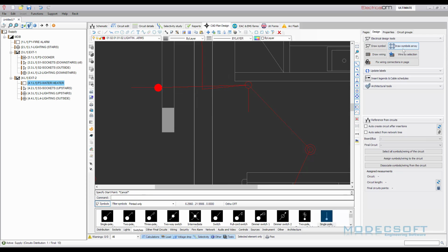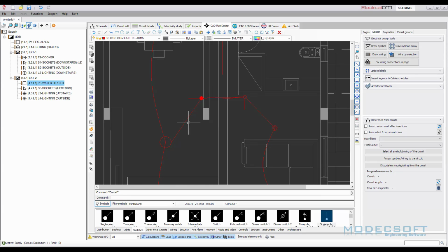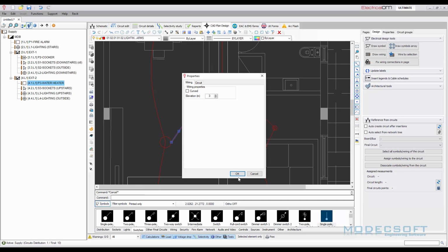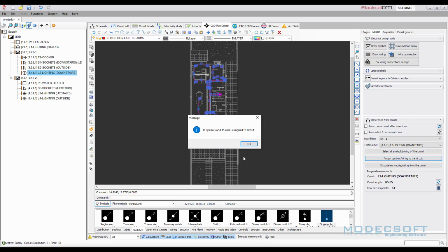I'm going back here and again from here. I want to go back to this lighting point as well. I can control the elevation by double clicking and fixing it properly. Okay, now because we have only one circuit for these lighting points, we can just select them all together and going to our tree network view, we can select this L2 final circuit we already include in our electrical diagram and assign it to these lighting points using the reference from circuits and apply the changes.